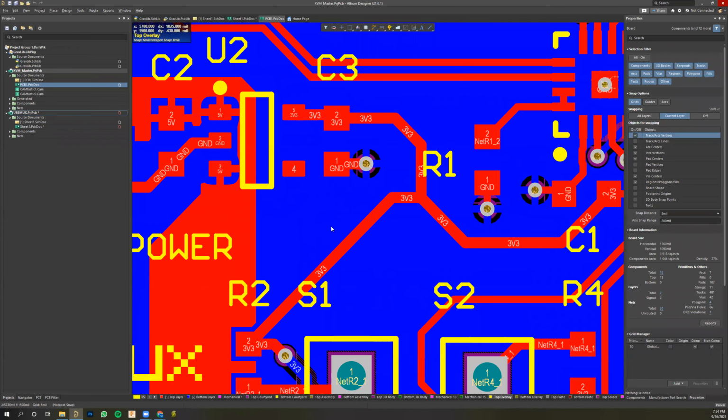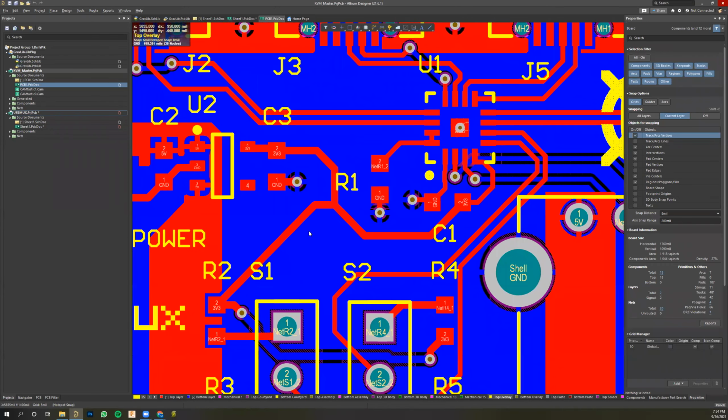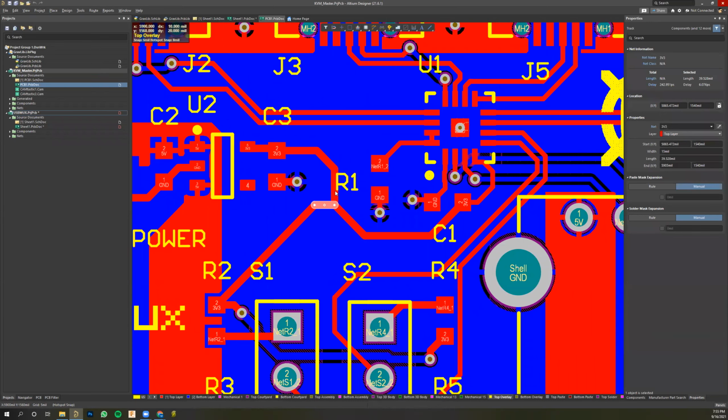I would do one thing different. I typically tell teams that anytime you're dealing with a power signal, to not use a trace. And here I've violated my own rule. I did a 3.3 volt trace. I made a Y, which is sad. But what I could have done and probably should do is create a polygon that's kind of a goofy shape. It goes around this pad, down here, around here, up and around here.